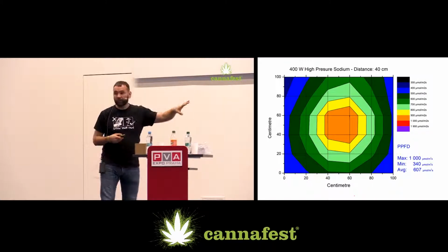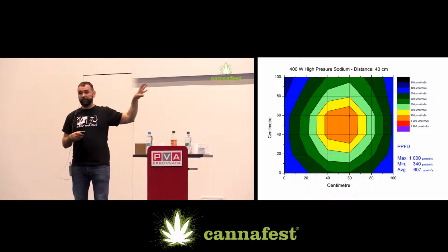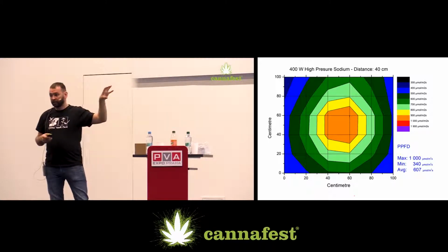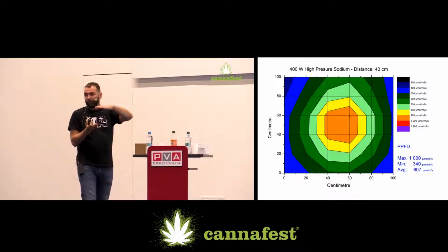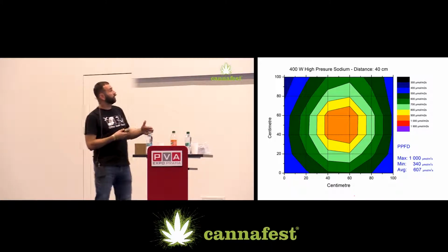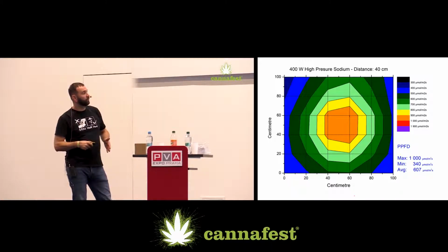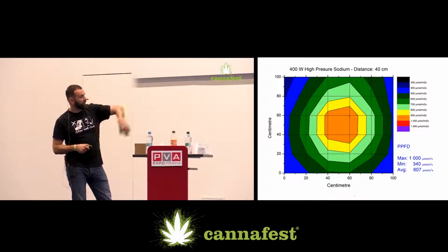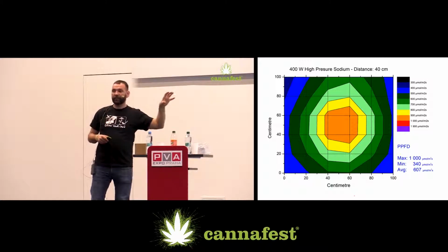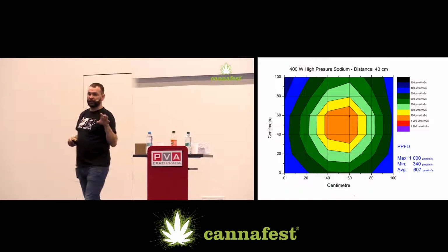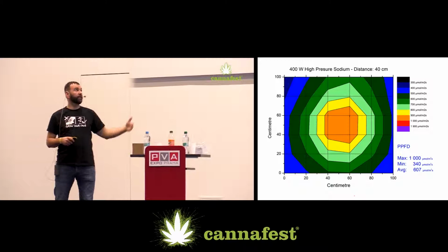Just as a matter of interest, if you increase the distance by just 10 centimeters, which is not much, the drop is 10% on the average illumination. If we use the foregoing picture, it's 676, while here it is 607, and it's only a mere 10 centimeters.